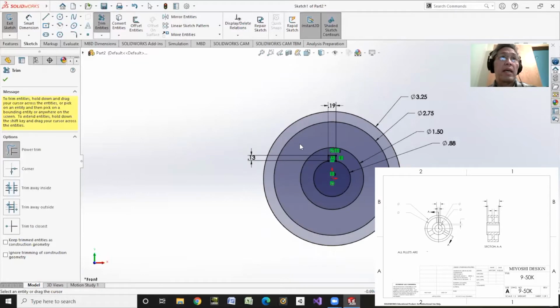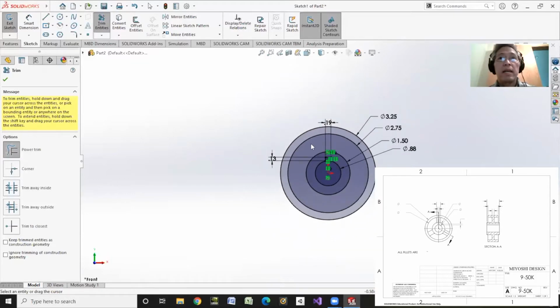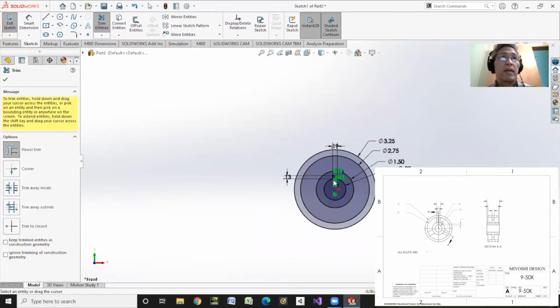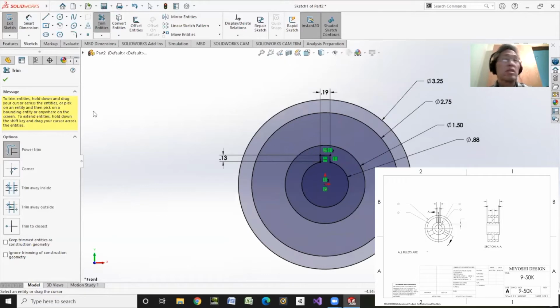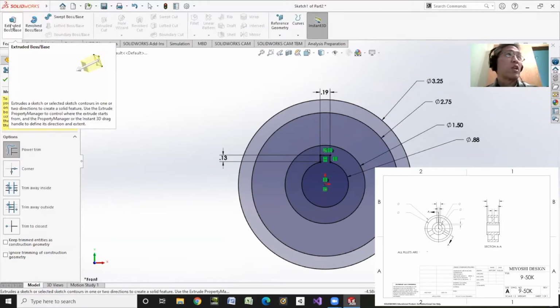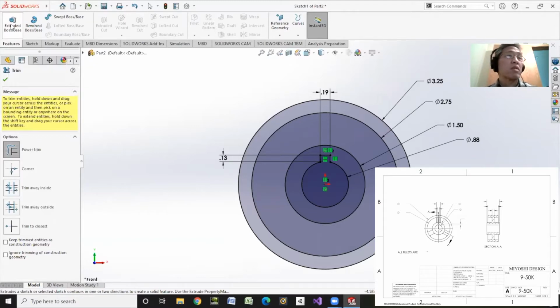Now I'm going to go ahead and dimension this guy here. Oh, I dimensioned already. I'm going to extrude it. So let's do this. Oh, I don't want to put those guys in. I'm going to extrude it first. So nice thing about SolidWorks, if you know what you're doing with what model you're making, you can do whatever you need to. So I'll extrude by space.